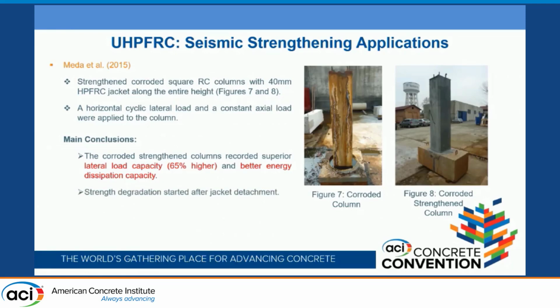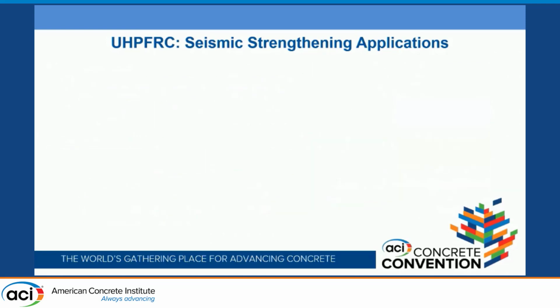He also reported that the strength degradation started after the jacket detached from the base, and he ended up with a very important point to be considered nowadays: corrosion is a very serious problem which can significantly affect the seismic performance of RC elements in general.